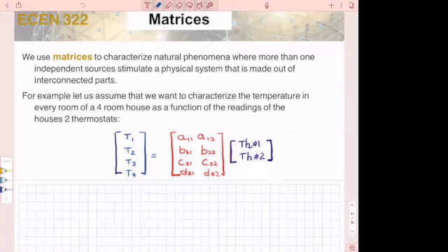A lot of times what people do, of course, there is a design ahead of time, all right? But those designs are not accurate. So the first time you occupy a building, nothing works in terms of temperature. Some rooms are totally cold, some other rooms you cannot be in because they are totally hot. So what people do, they play with the thermostats. They go and do a number of experiments. They put different settings, say if you have 3 thermostats, you do 6 different possible combinations, all right? So you put a range of values and then you develop different combinations. And then as you set the thermostats, you go and measure the temperature of every room, all right?